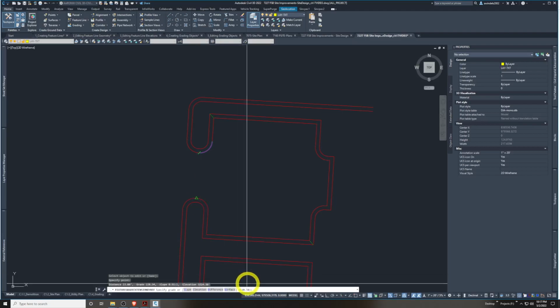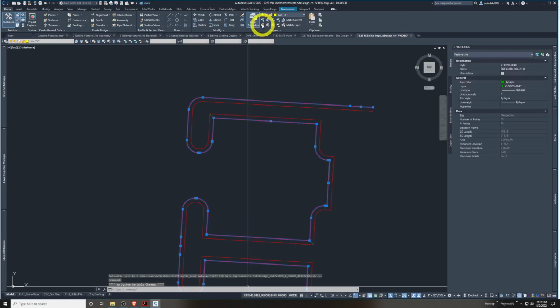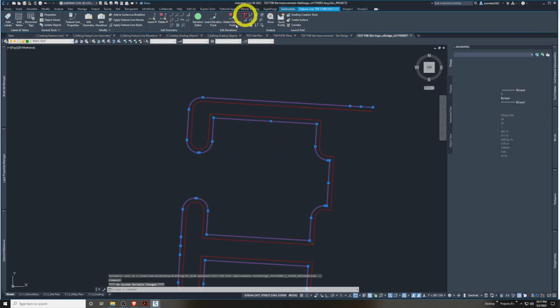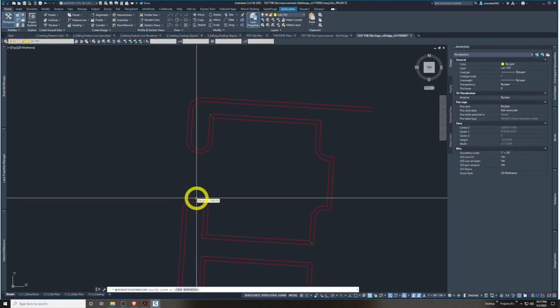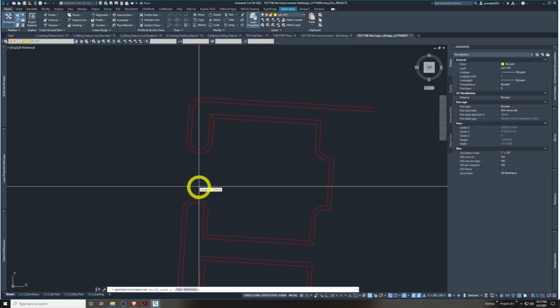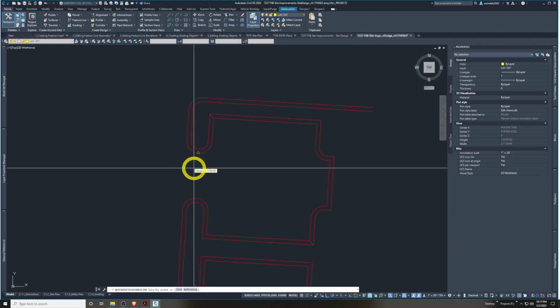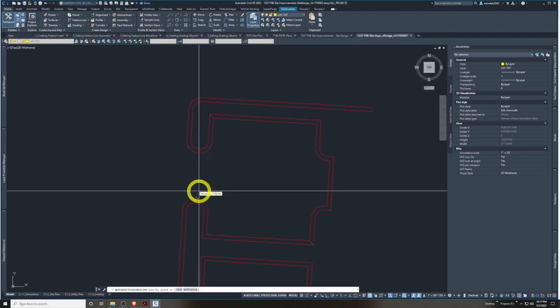I pick it, and it's like 110. Let's just say I don't want that. I just want a -2 grade. And if I check these with my quick editor now, 3189 and 3188.54, that seems like about 2%. So I fixed that. I made this go down 2% across with an extension.